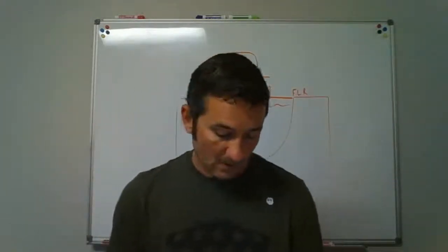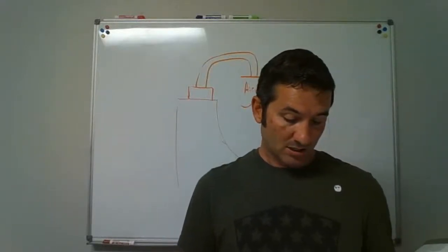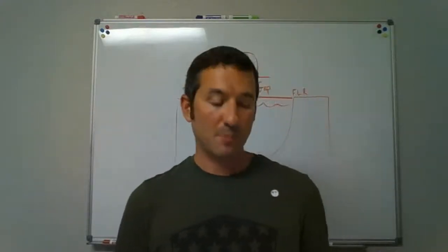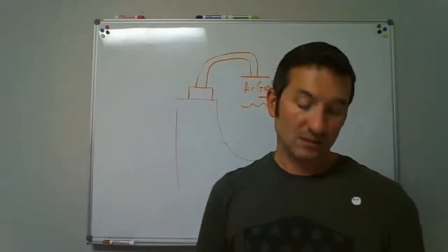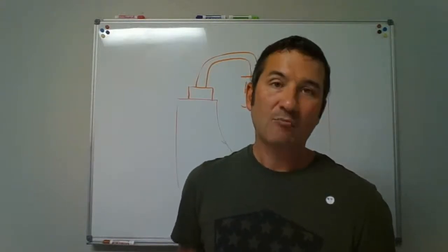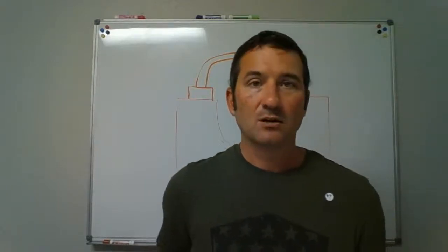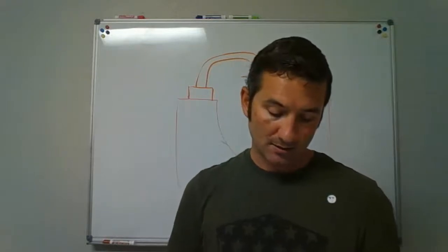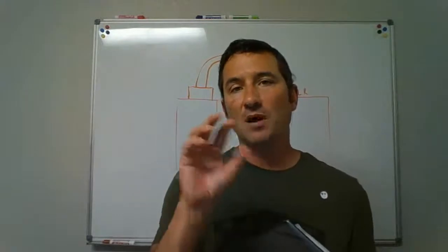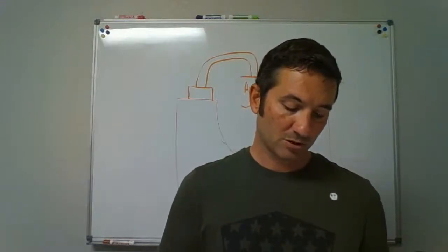And your last one, question 15. Non-potable distribution piping needs to have pipe identification every 25 feet. If you've got non-potable distribution piping, you need to have pipe identification every 25 feet. Is that a true or false statement? I would look around 608.8.2 to find that, to see if the spacing for the pipe identification is every 25 feet on that non-potable distribution piping.